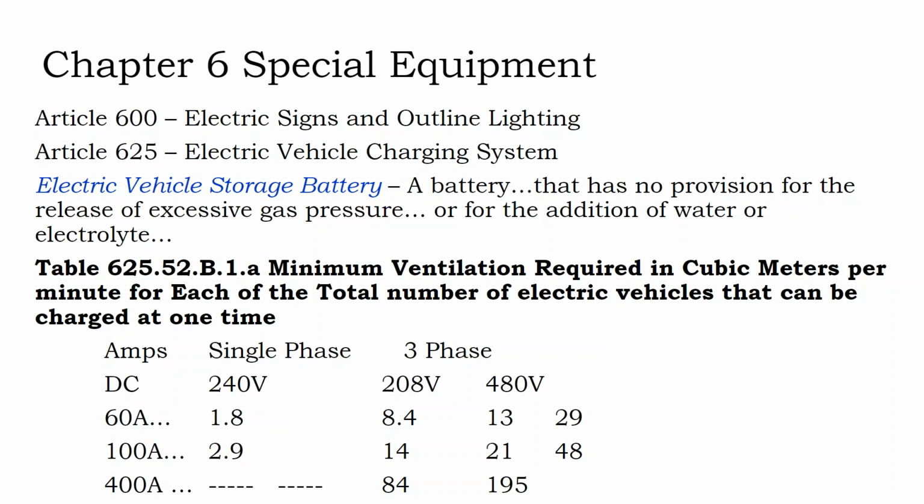Higher ends might have 140 or 150 kilowatt hours. I don't really know, but it's around that range. And so once you're getting into home-sized lithium-ion batteries, just the volume of chemicals in the battery is saying you need to be able to ventilate this room, even though the batteries are sealed and not producing gas.